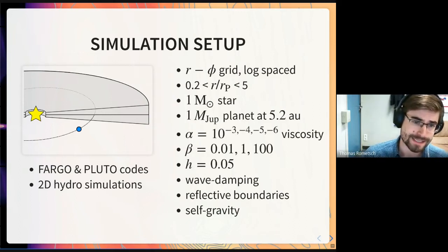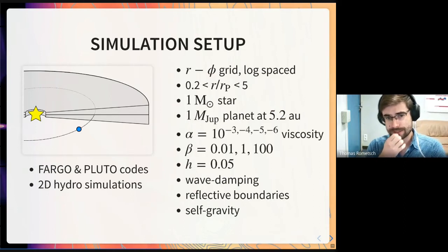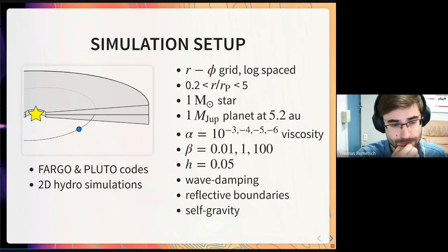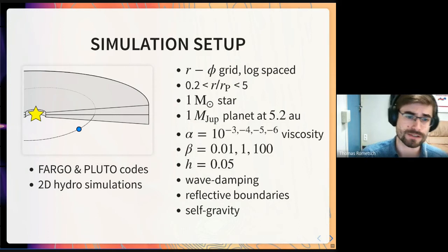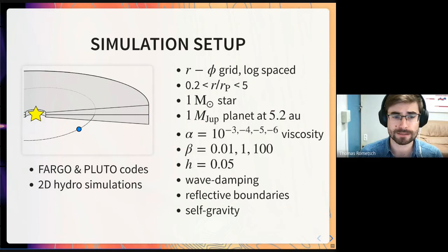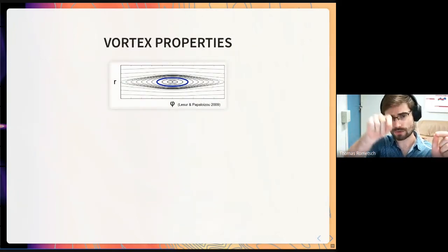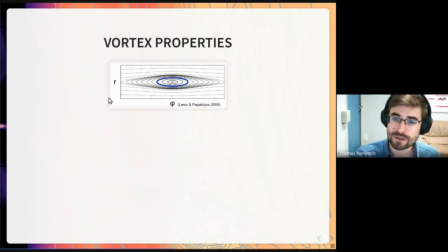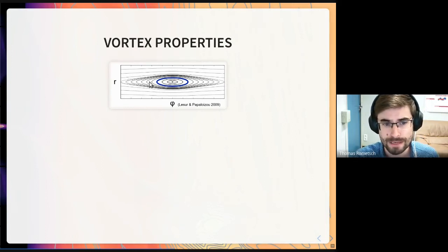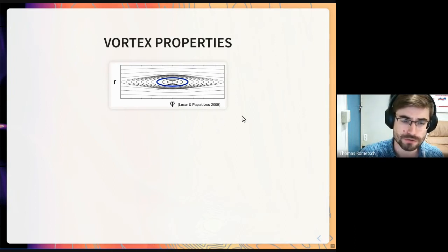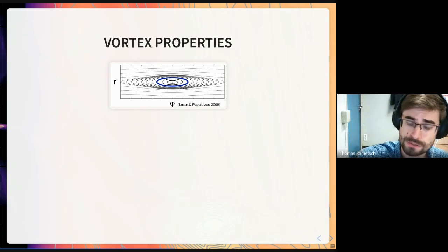Now, for all the later results I show you to make sense with the vortices, I just want to make sure that I introduce the basic concepts here. Like I said, vortices are things that swirl around. Here you have an R phi plot of streamlines. This is from a more or less theoretical paper where they plotted the streamlines of a vortex solution. Vortices are solutions to the Euler equations, or to the Navier-Stokes equations also.